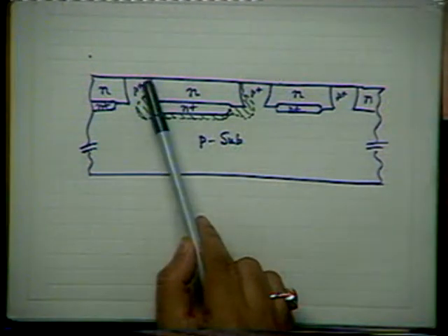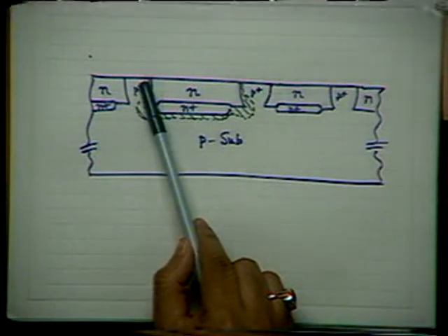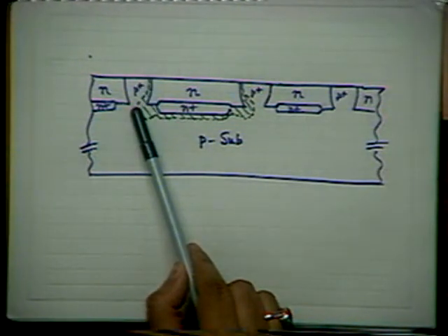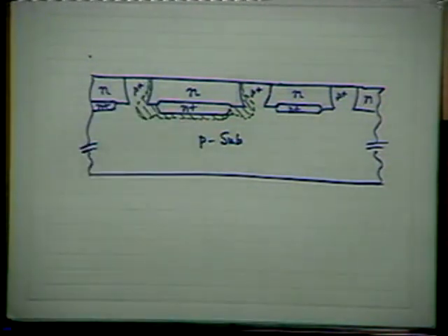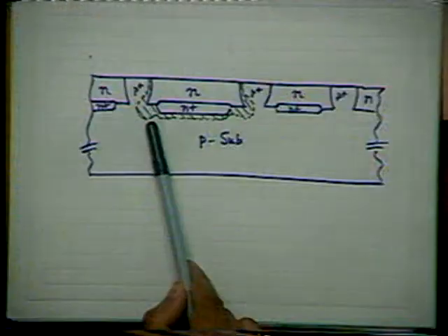So near the surface, boron concentration is very high compared to the bulk, in the depths. So the depletion layer width, being inversely proportional to the square root of doping, should be minimum near the surface and maximum near the bottom. And what about capacitance per unit area of junction? That should be maximum therefore near the surface and minimum near the bottom. Am I correct?